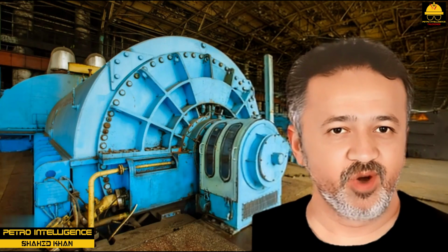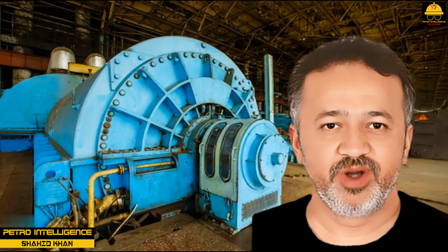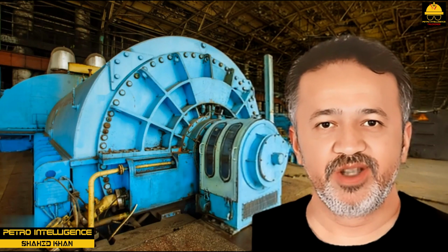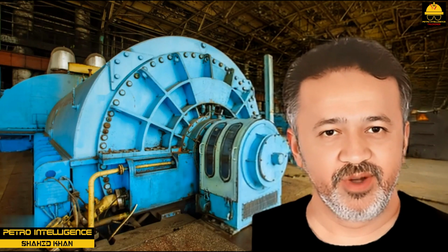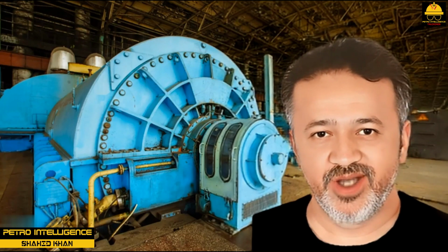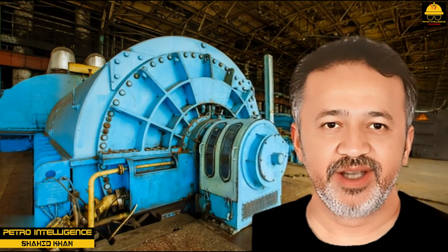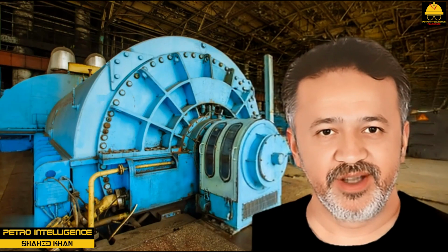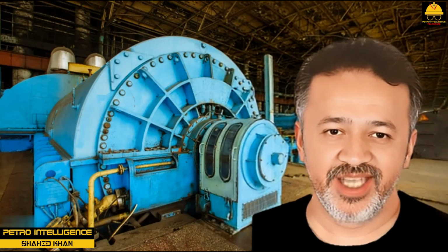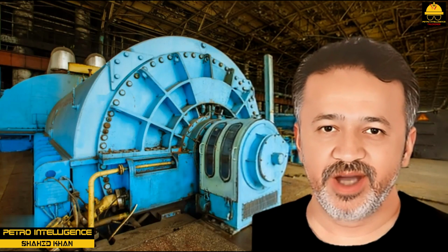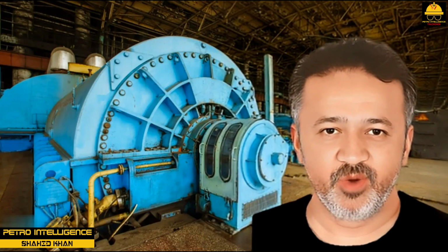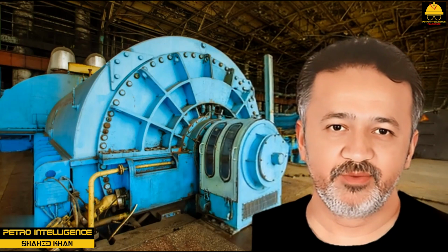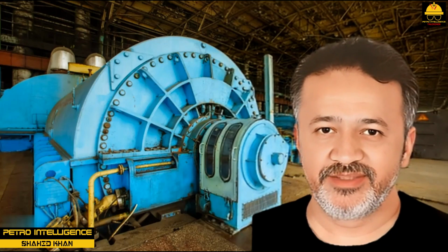Electric motors are used to operate pumps, generators, compressors, fans, blowers, and other equipment. The operation of an electric motor is based upon three scientific principles. Electric current creates a magnetic field, magnetic poles attract and repel each other, and current direction determines the magnetic poles. An electric motor consists of a stationary magnet or stator and a moving conductor or rotor. A permanent magnetic field is formed by the lines of force between the poles of the magnet.